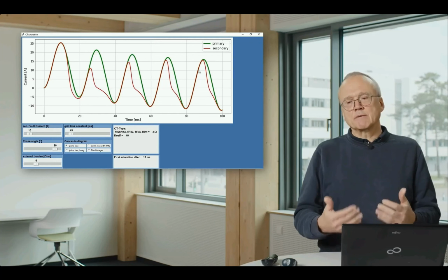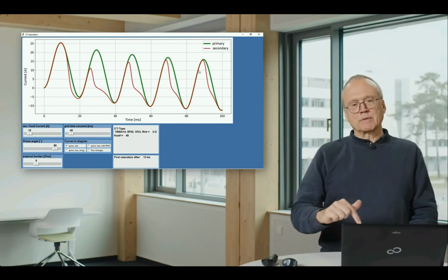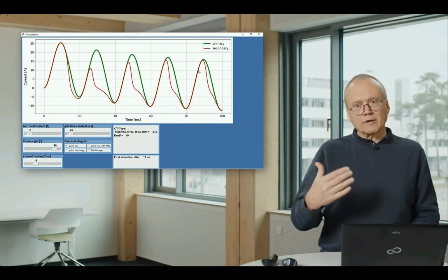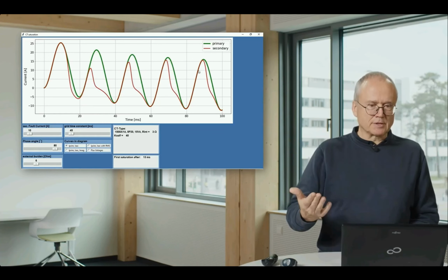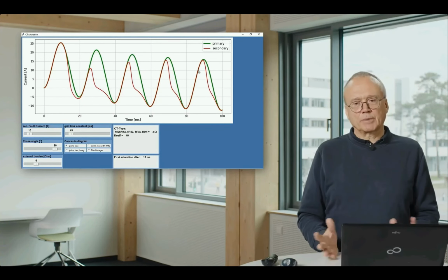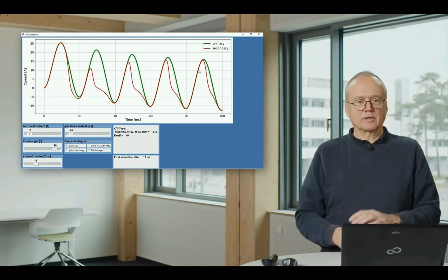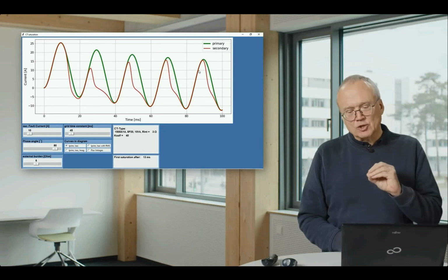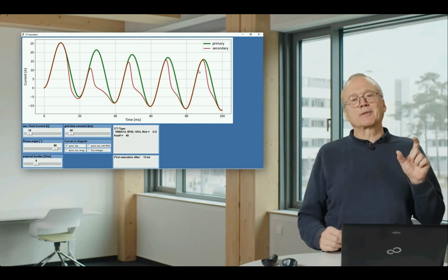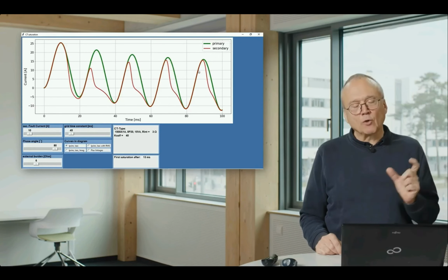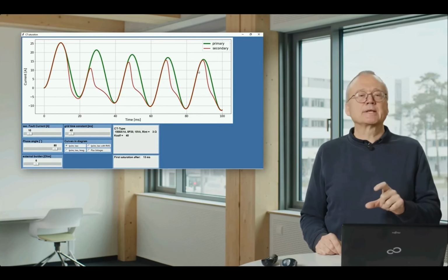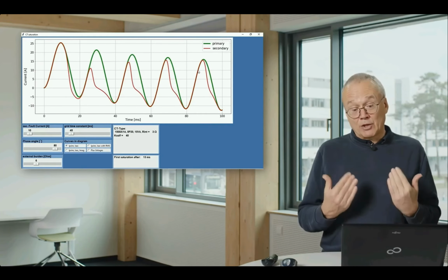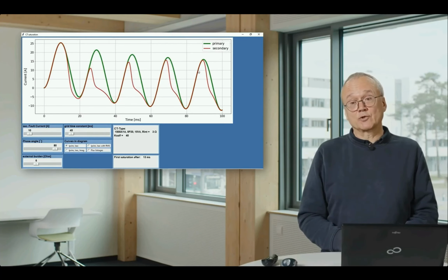If you are, for instance, in a medium voltage system, just on the medium voltage side of a transformer and make a short circuit there, or if you are in a transmission system close to a power station where you have the unit transformer and make a short circuit there, then the short circuit current is mainly limited by the transformer reactance or the transformer impedance. And transformer impedances or generator impedances, they have a long time constant. And there you may end up in 200 milliseconds or even more.